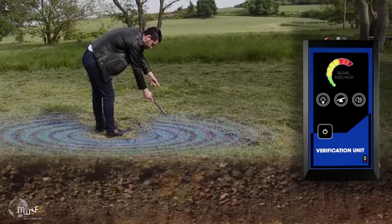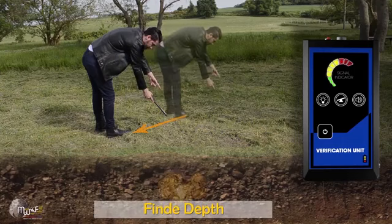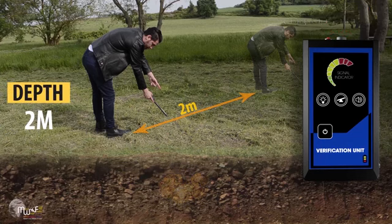How to determine the depth of the target with the Ionic system. The user should stand above the target point and the device must be oriented vertically. Then walk from the target point in another direction. You will notice the indicators gradually decrease until they stop. Then measure by meter from the last sense point to the target's point, and the result is the depth of the target.